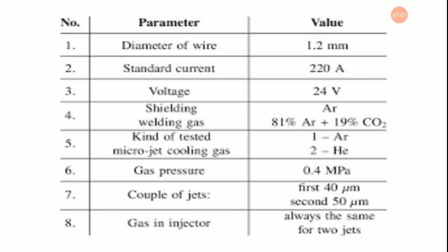The base metal used in this study was AA7075 T6. It is in the form of rolled sheet of thickness 3.46 millimeter. The welding of AA7075 T6 usually involves using a non-heat treatable filler material such as ER5356 to increase the hot cracking resistance of the weld fusion zone. So in this study, we selected a commercially available filler wire, that is ER5356.